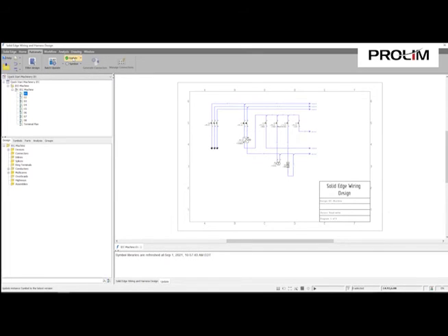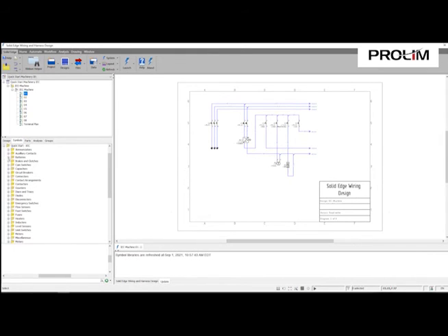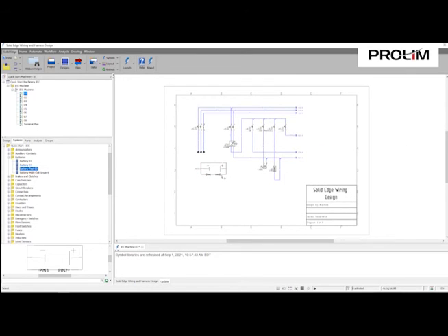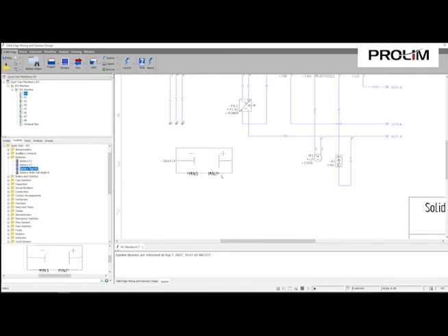I don't really know if it's even doing anything or not, but now if I go over to the Solid Edge tab, everything is refreshed, or at least it should be. So now if I go over to the Symbols tab and go down to the IEC, the Quick Start, and open up my batteries, we can see that now we have this battery 3 test. Here's a quick preview of it. So now I can just drag and drop. I can bring this over, put it wherever I need to put it. And again, maybe this scale isn't perfect, but I can manipulate and change that all within the symbols library. So again, just a very simple way to create a symbol and then have access to it to pull into a diagram all within a minute or so.